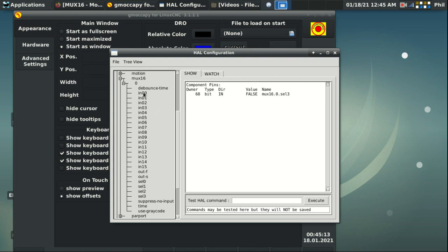And the MUX16 also allows you to output either floating value or an S32 value. So you can output a signed integer value with the MUX16, whereas the other multiplexers were floating output only. So we have a floating output value, a signed integer value, and then we have 4 buttons that we would have to assign.